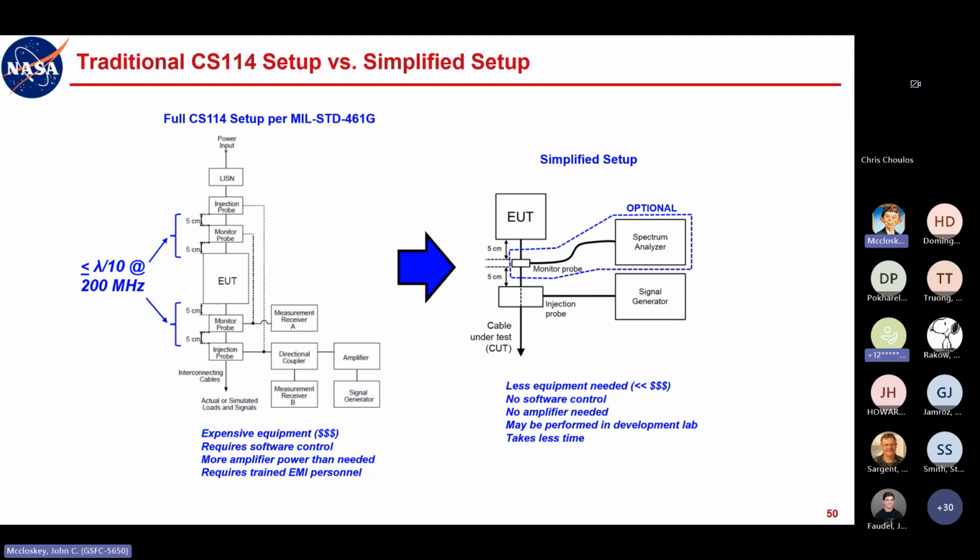So if you fat finger that and go to full scale while you're running a test, and what you want is 108, 109 dB microvolts, but the maximum you can get is 120, you've only got about 10, 11, 12 dB of headroom there. You're basically not going to damage anything if you go 10 dB above your intended test level.